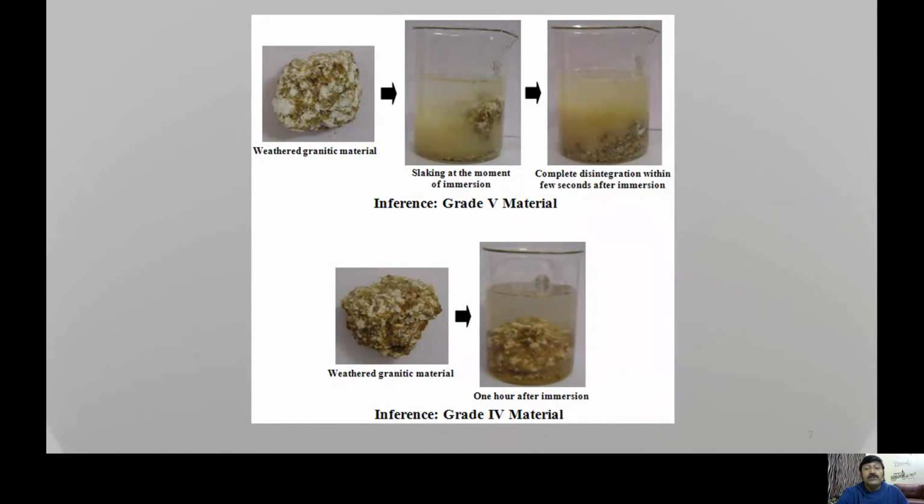However, we are not so lucky for other adjacent grades, and therefore we have to depend on some quantitative measurements. It cannot be solely based on the subjective criteria as given in the table of the six-fold classification. But we have to remember that the first thing to categorize the weathering grades is to follow the six-fold classification scheme. Then we can refine that classification with the help of some quantification methods, like index tests.